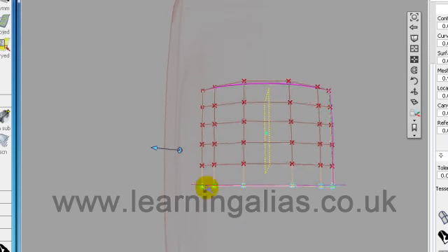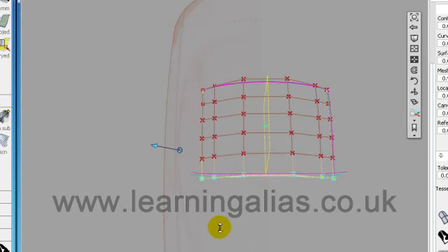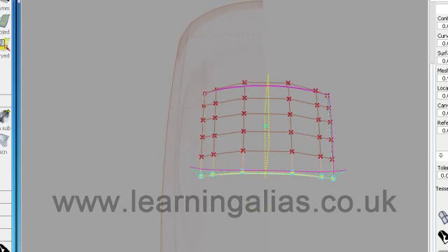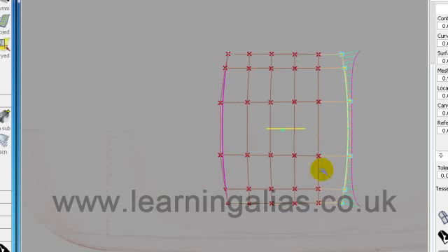Instead of looking down the plane like that, you just move it to, say, there, with your point of focus there, and then take the Planarize Hull tool and zap it. And then if you look at it again in F5, you'll see you've achieved what you needed.